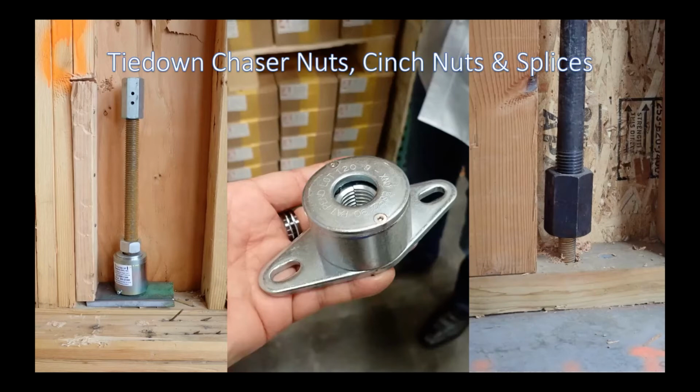permanently. In the example on the left, with those types of cinch nuts, they usually load the building down, finish the building, and then come back and press a spring, which then activates the ratchet action. So you can't activate that too soon. You want to activate it late so that it has enough residual movement to take account of future depression, movement from shrinkage, compression, live load, say dynamic activity, anything that compresses. It will then take it up and keep on locking the building down as it goes.